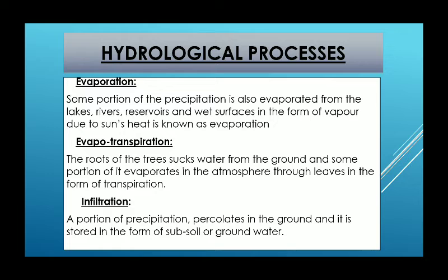This transformation occurs when some molecules in the water attain sufficient kinetic energy to eject themselves from the water surface. The main factors affecting evaporation are temperature, humidity, wind speed and solar radiation. The direct measurement of evaporation is desirable but difficult, and possible only at point locations.